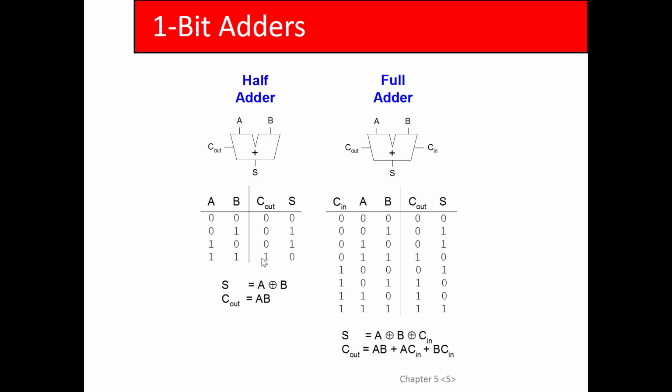The sum bit is going to be a modulo 2 operation, meaning that in binary, your sum bit is going to be 1 whenever you have an odd number of input bits of the 3 inputs, right? So if you have, for example, 001, 010, 100, that's 1. One of the 3 inputs is 1.